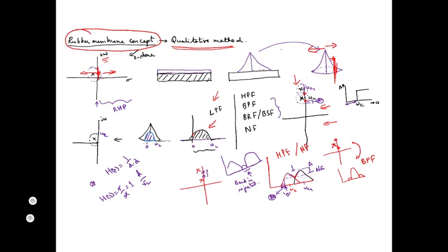On the other hand, if you consider the pole this way, if I am placing it nearer to the axis, you see the amplitude is high, and as I move it, the amplitude is reducing. Okay, so in this way we can have an understanding of how the placement of the pole and the zero affects our frequency response.